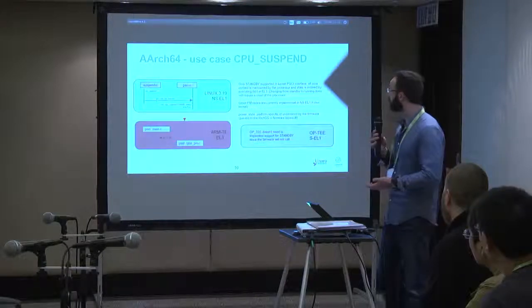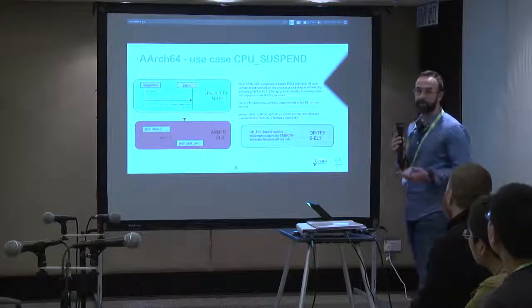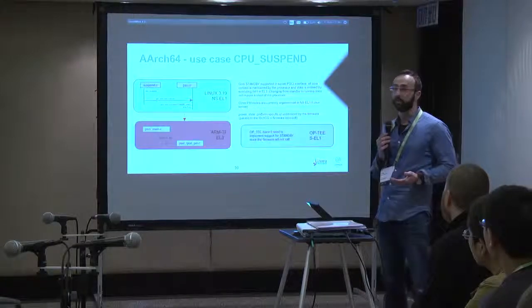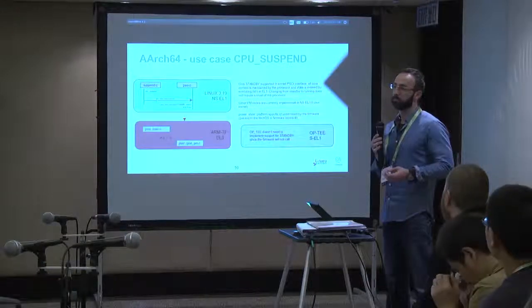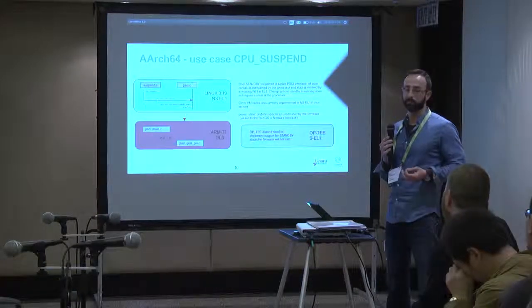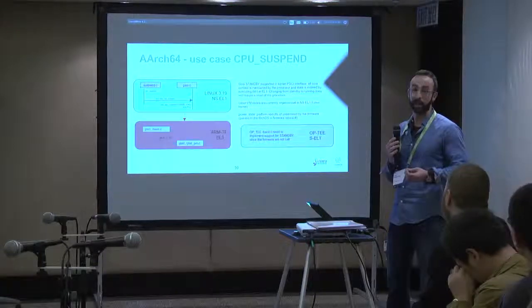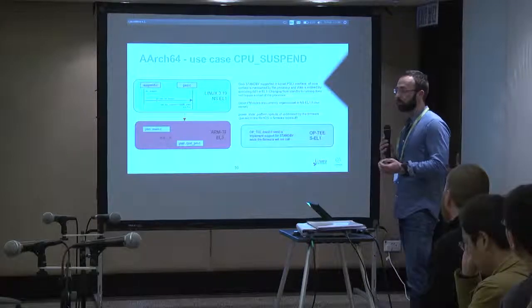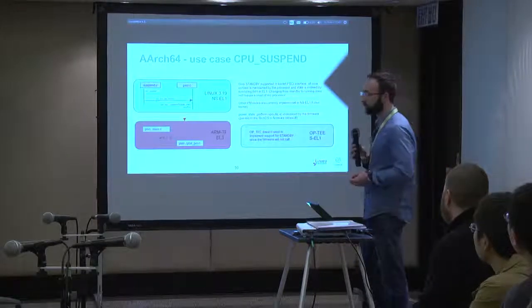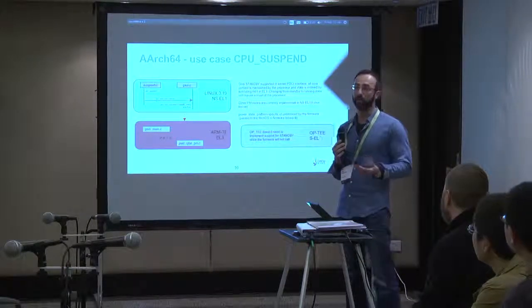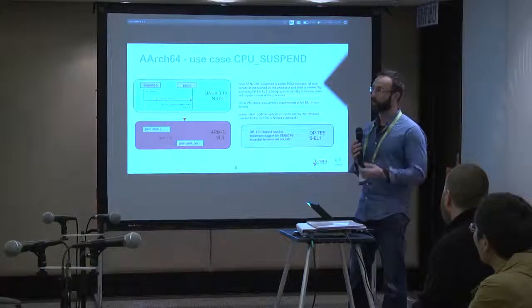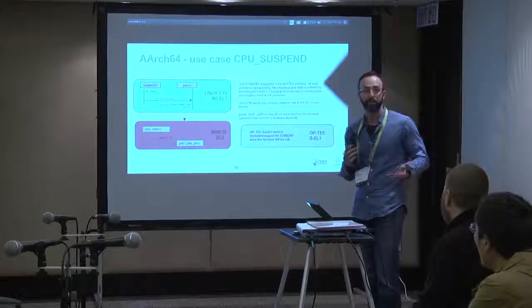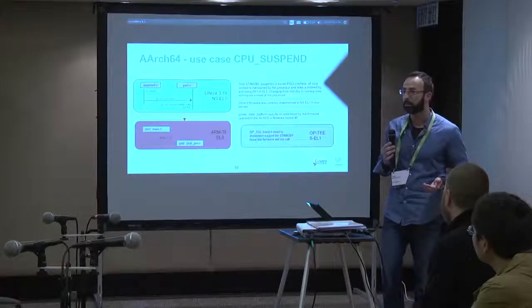I don't know if there is, in the next version of the PSCI spec, a provision for that, basically to ban the firmware from powering off clusters if that request doesn't come exactly like that from the kernel. But in principle, if you switch off a couple of the cores and that's all there is in the cluster, the firmware will shut it down. And I think maybe the kernel wouldn't be happy with that.